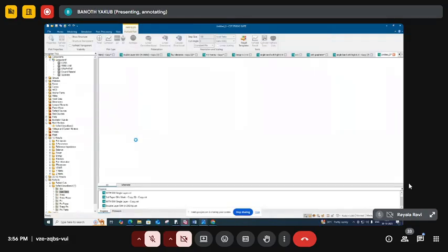In parametric analysis, we designed the cross slot shape, but we can change to another cross slot. We can see that response also. Basically, the main things in parametric analysis are material thickness and changing the materials we are taking for the antenna design, and the microstrip feed line design. In this design we are taking a rectangular microstrip feed line, but different feed line options are also there.